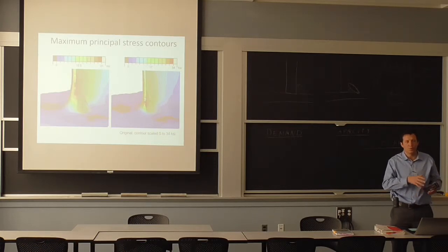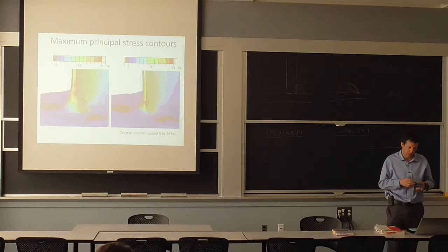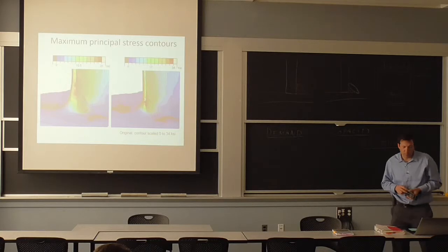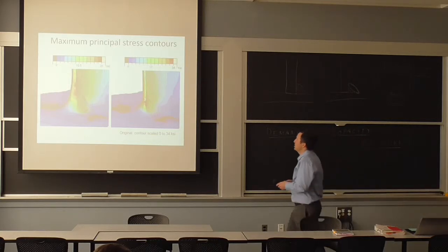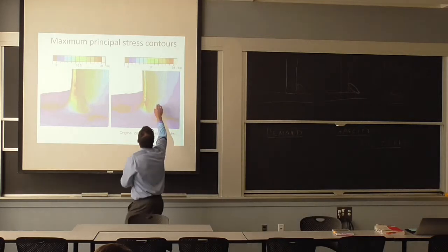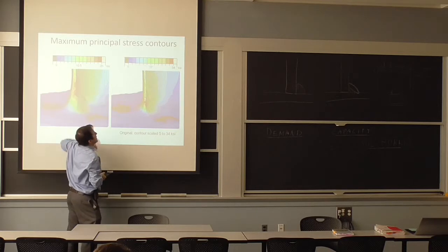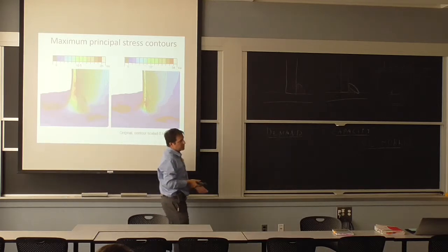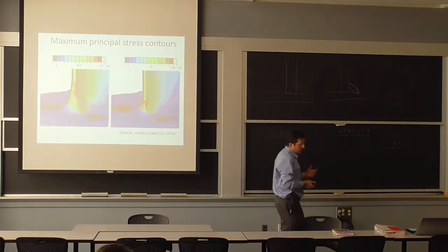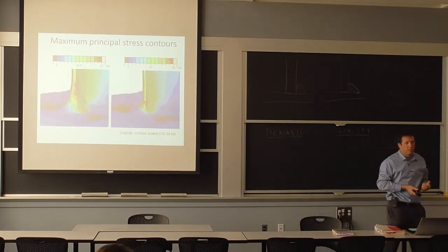build it up to the new generation is very appealing, because they were thinking about more or less of a welding process, an additive manufacturing process to add material here. Now, I think you could probably see, and this is where these two scales are different. So this one goes to a stress of 34 KSI, and with the new design you were going to 21, and you were moving this up. So you're looking at about a 50% reduction in the stress level.